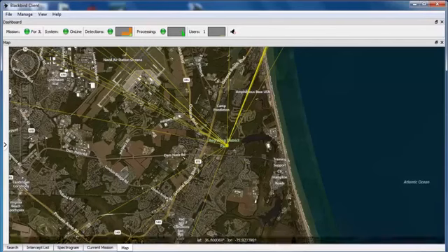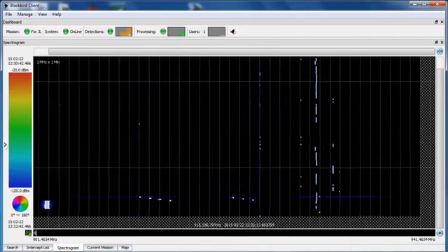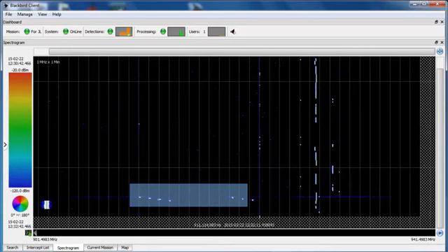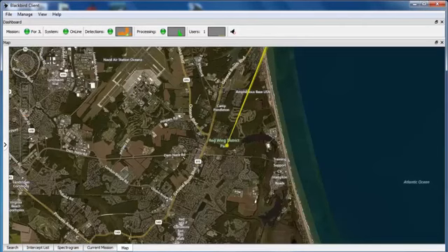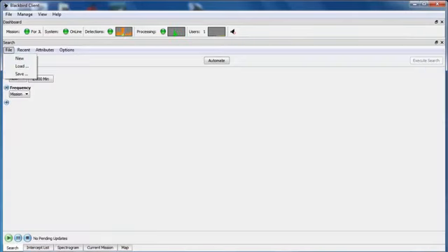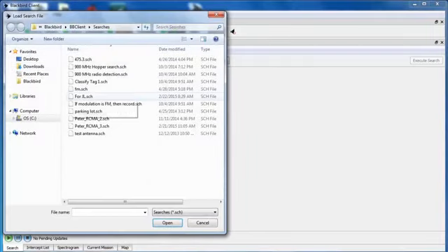I can also clearly see the frequency hopping nature of this radio on the scrolling spectrogram. If I zoom to this set of emissions, you can see that the map display now only shows bearings to those signals to which I have zoomed on the spectrogram display. Rather than zooming, a simpler approach would have been to have set a preset detector for this type of signal in which I am interested.